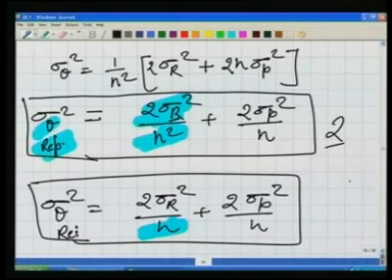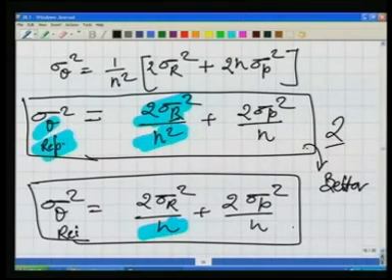So the error propagated in our final angle value because of the reading is less. That means the angles which we observe by repetition are better than the angles which we determine using the reiteration.